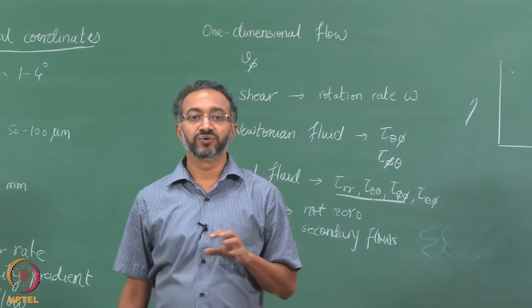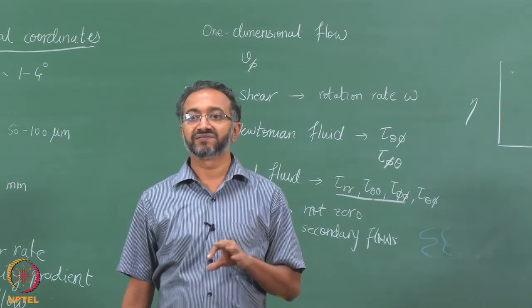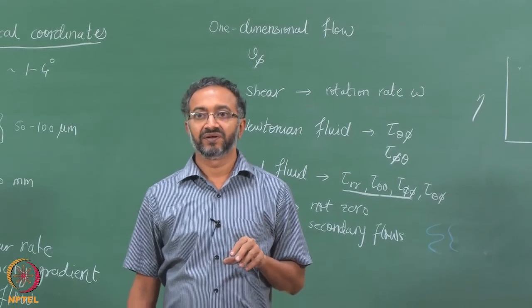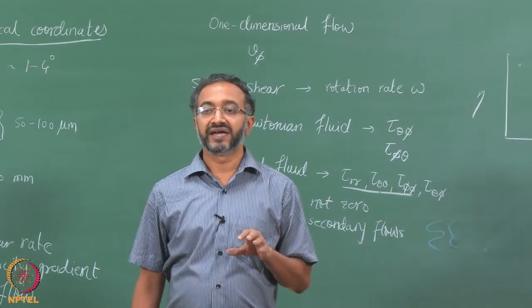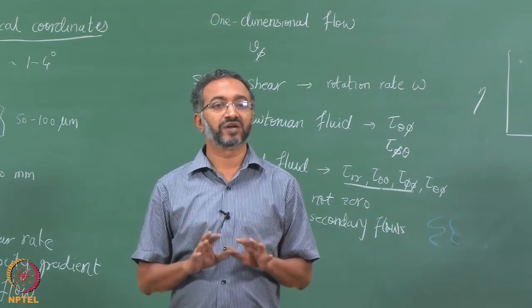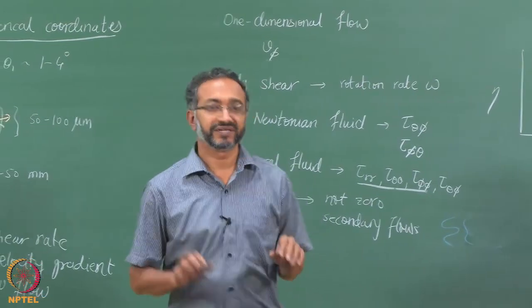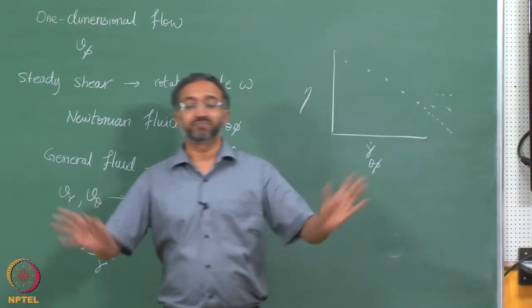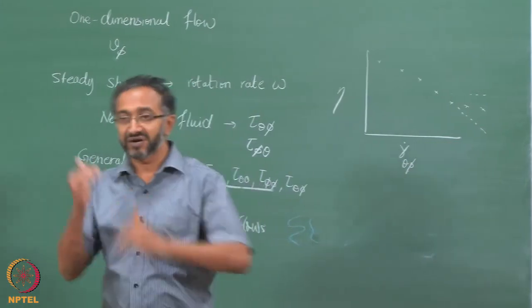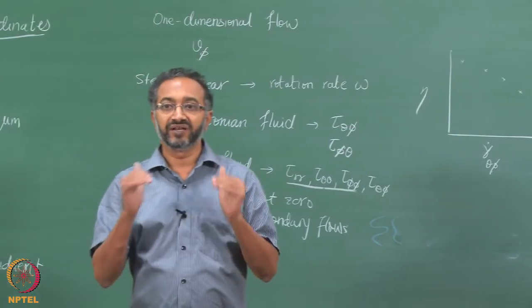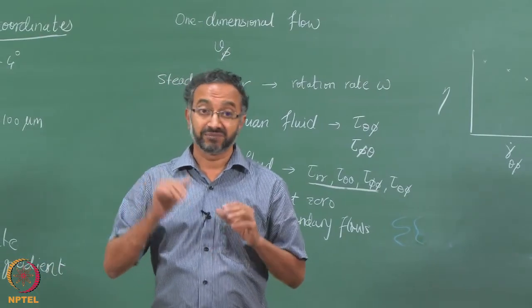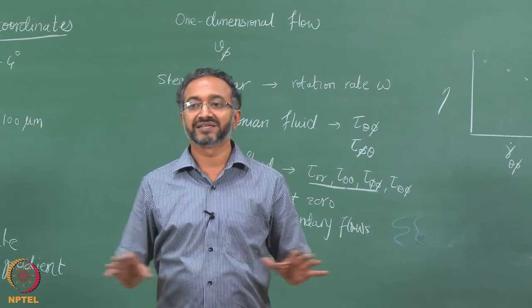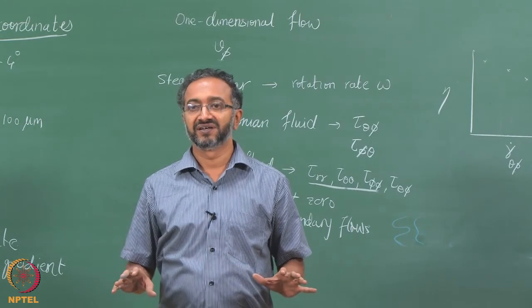The other thing you can do is to try to do experiments with different geometries, because any material behavior should qualitatively remain the same. So, for example, if this flattening out is a real phenomenon, it should not get completely different in two different geometries. Quantitatively it may be different. So, any feature that you want to claim as a material phenomenon will remain the same in different geometries.